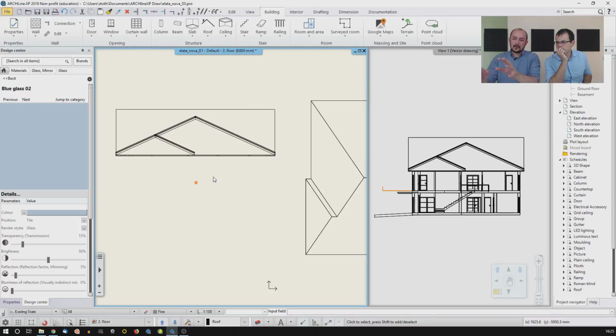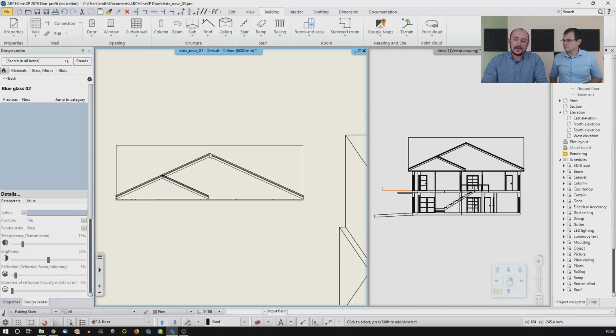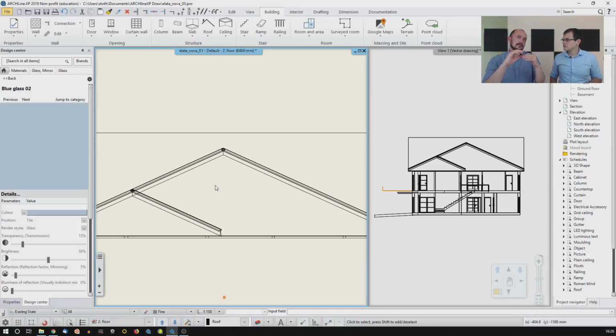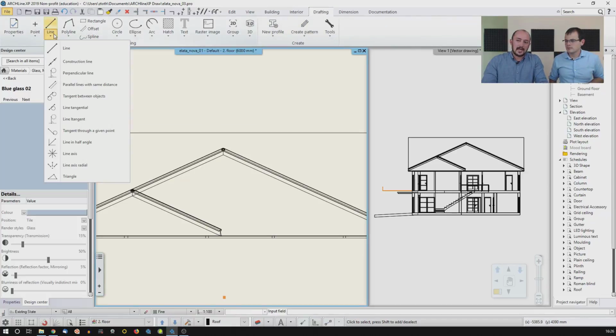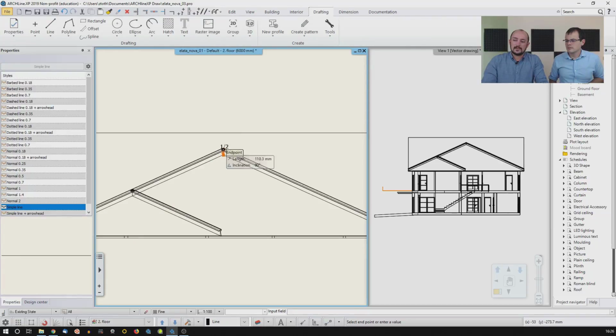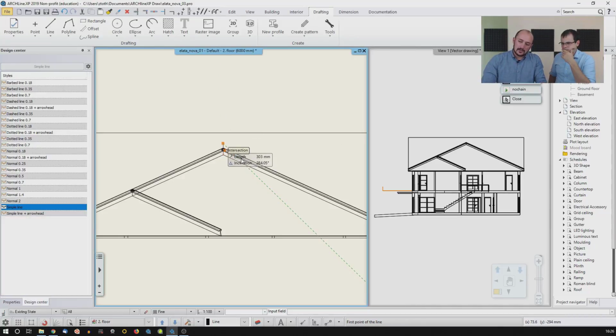I just made a snapshot or a copy of that content there, which will tell me what exactly is the shape of the contour that I'm willing to follow. And I know that what I would like to create is 100 millimeter larger than the original contour from this point. Yeah, 500. Sorry, 500. So I use the drafting tool, and I use, for example, the line. Now, this is not the only solution. I just use this solution from time to time. I just click on the starting point. I just move the mouse upwards, and I type 500 because now I'm in millimeters. So I hit enter, and then I have that appearing over there.